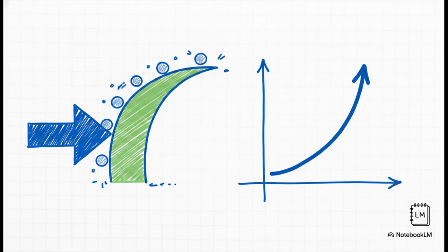So what happens if we just keep pushing the voltage up right past that valley point? Well, normal diode behavior simply kicks back in. Once the applied forward voltage gets high enough to completely overcome the barrier potential of that depletion region, the quantum tunneling stops entirely. From that exact point onward, the device just acts like a regular old PN junction diode, with the current increasing normally as you turn the voltage up.